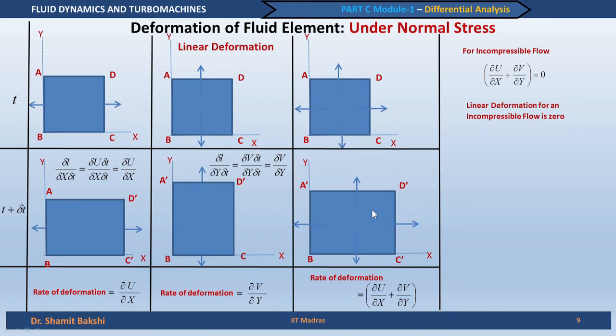If, for example, you go from here to here and the density decreases, then the volume can increase by keeping the mass constant, but that is only admissible when you have a compressible flow. For an incompressible flow, this is not possible. So, this part we do not have to bother about, because we are considering incompressible flow.